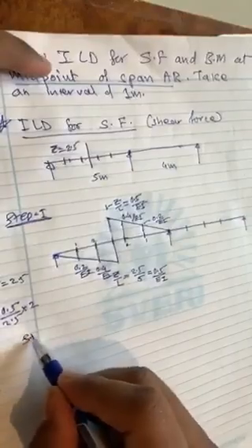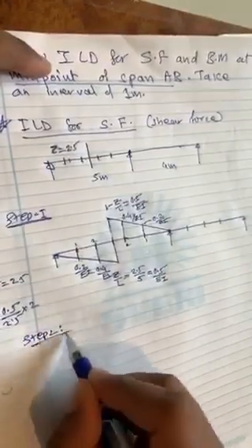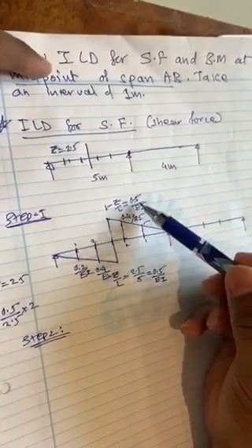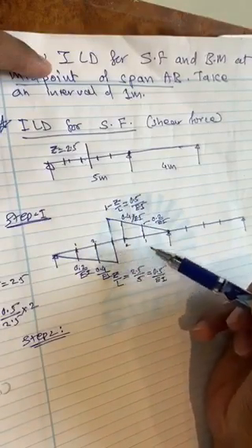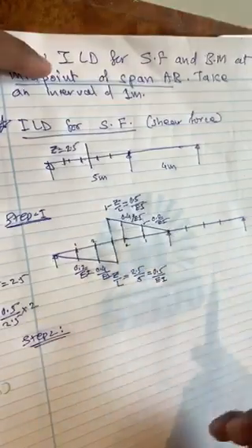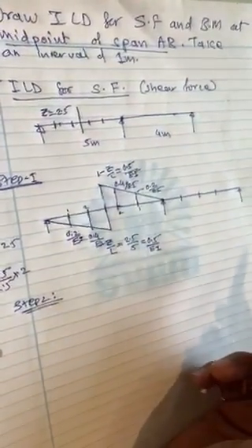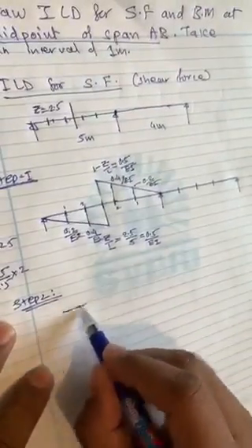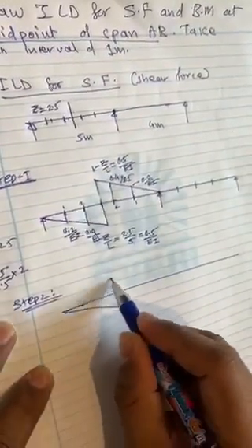So let us go to step 2. What step 2 suggests is that because of this determinate 0.5 by EI, 0.5 by EI, we have to find how much fixed end moment generates, and because of that what will be the end moment. So I will draw this diagram quickly.